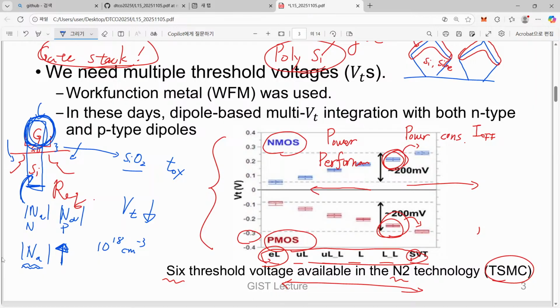Please remember that the order of our doping density for source and drain is about 10 to the 20 per cubic centimeter, and we are now trying to go beyond 10 to the 21 per cubic centimeter. So 10 to the 18, especially with leading numbers not 1 or 2, but if it goes to 5 or something, then this becomes really comparable, non-negligible, even compared with this high doping density. That was quite problematic.